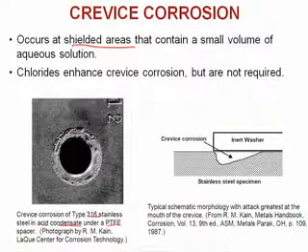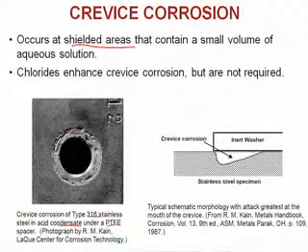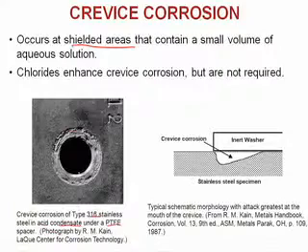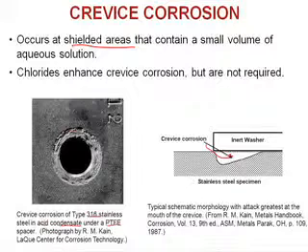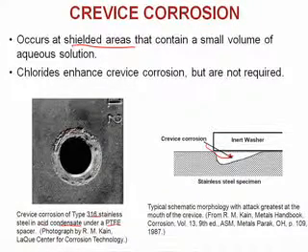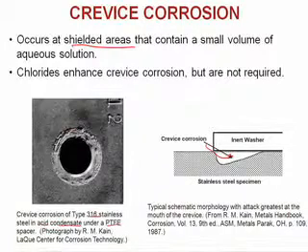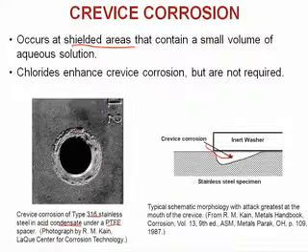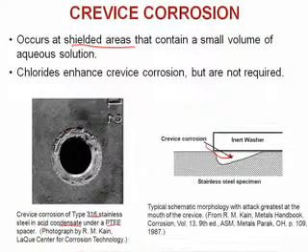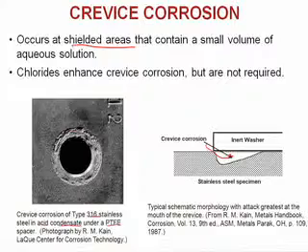In fact, we have some numbers that were stamped into the surface for identification. They look fine. But the corrosion, rather severe corrosion, happened in this creviced area, in the area underneath the washer where there was limited access of the exterior environment. That's a crevice. And in that region, we have essentially these same reactions that happen in a pit. In fact, they happen more easily in a crevice. So if you can design structures that are going to be in corrosive environments without crevices, try to design them without crevices that can cause this type of corrosion.